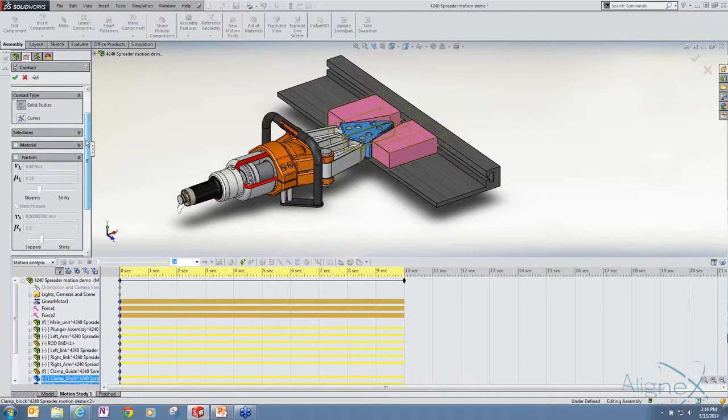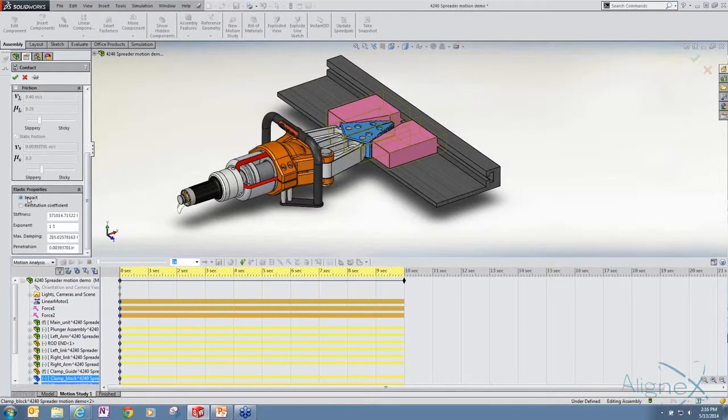And then when we turn off the material and friction, we actually can manually edit these values here. So you see once you select a material, it defaults to that stiffness between the two materials, and also gives us an exponent that controls the equation being solved here. So there's two different types of the manual contacts that we can set up.